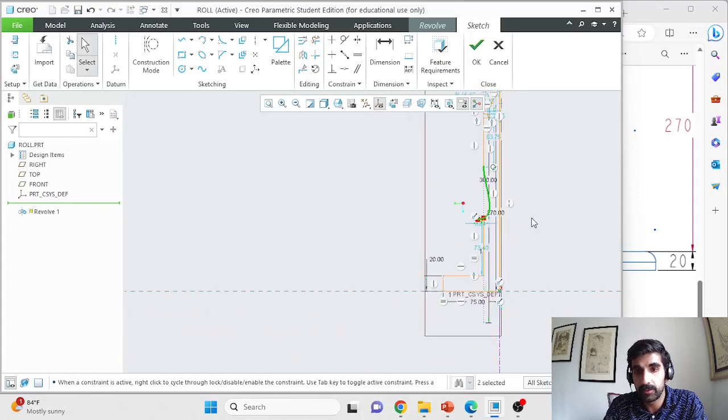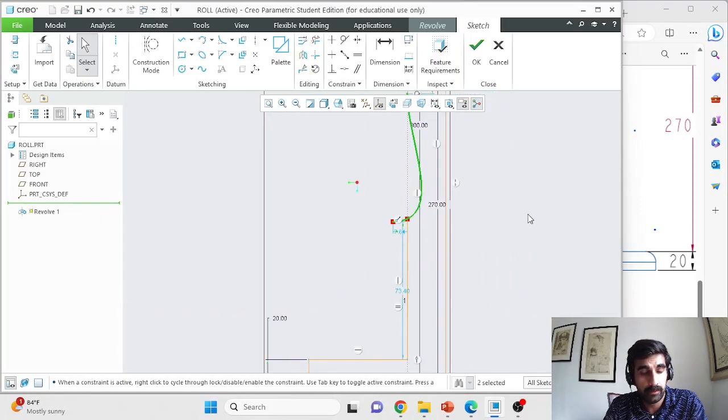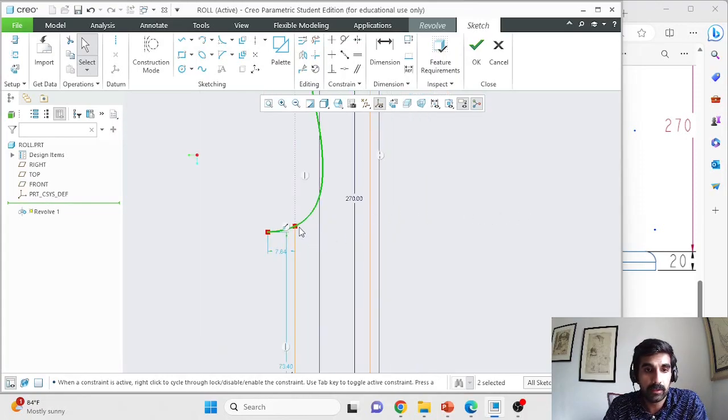When you press the center mouse button, you don't get the central area highlighted pink, which obviously tells you that it's not enclosed, and that's because of these two open edges. So what you need is to get rid of this additional curve sticking out. For that, you can use the delete segment feature.